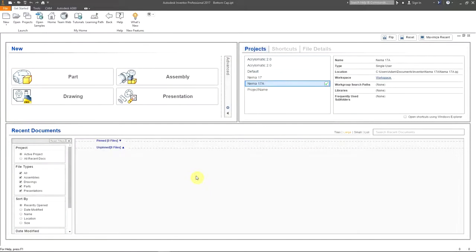Now that we've created the base part, the bottom cap and the top cap, we're going to bring that into an assembly. Once we've got it in place in the assembly, we're then going to make an in-context part for the body. What that's going to do is use all the geometry from the bottom cap or the top cap, whichever one we happen to use, and it's going to create a new part. So all the parts will be associative, meaning they're referenced off other geometry.